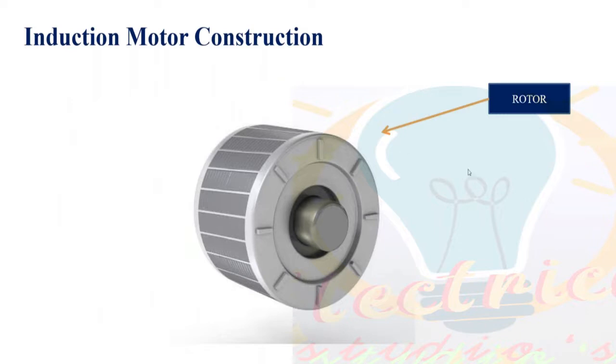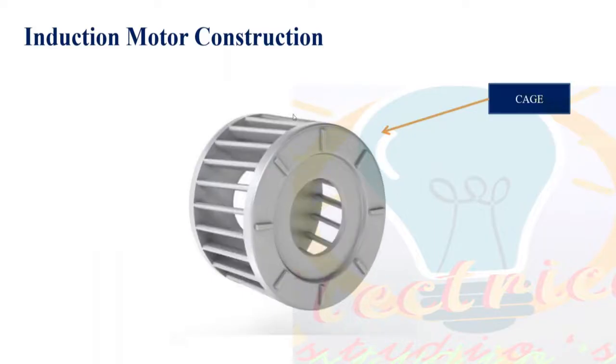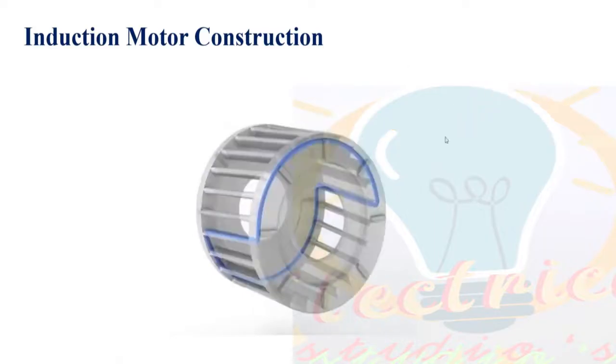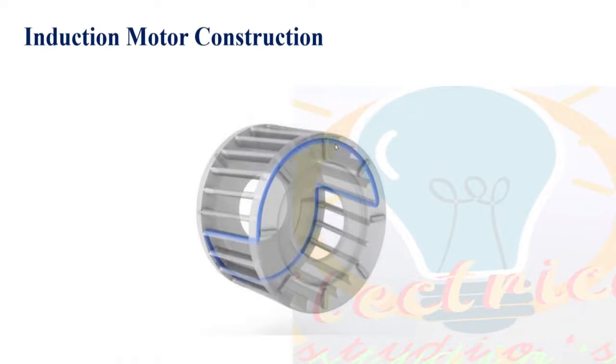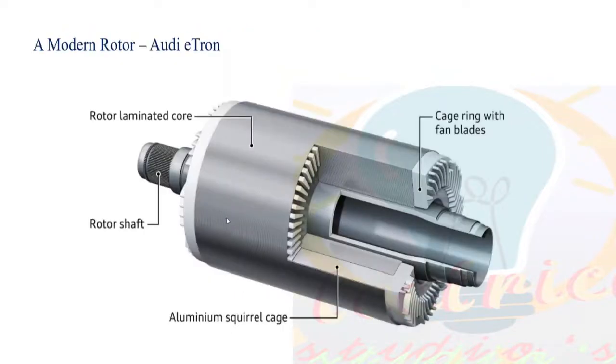The same stator that I use in a PMSM motor can be used in an induction motor also. So when I open an induction motor, I have the rotor and the cage, the squirrel cage, as we call it based on our textbook knowledge, with shorted ends. But today the modern rotor is not looking like this, which we see in the textbook. This is what the rotor of an induction motor looks like currently.